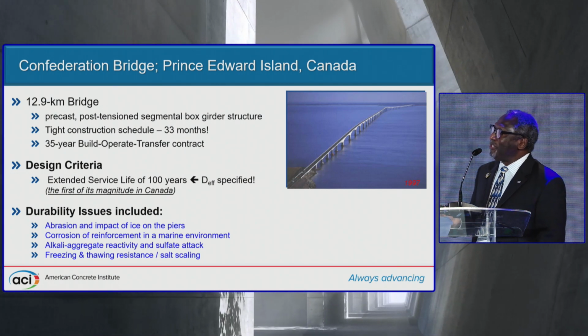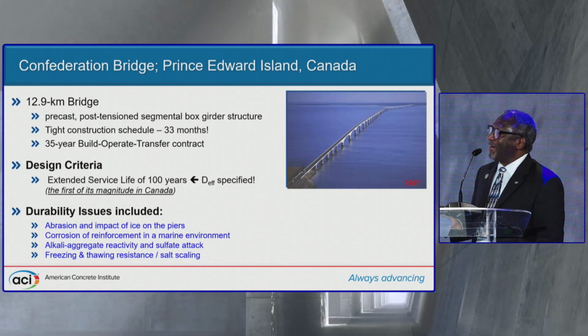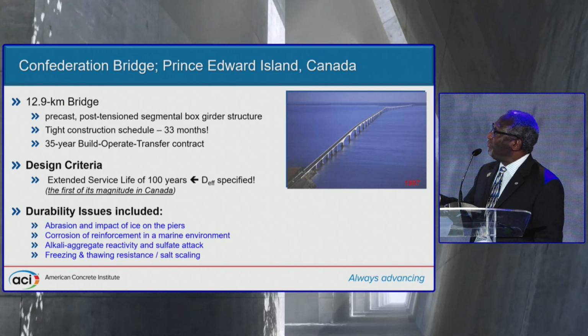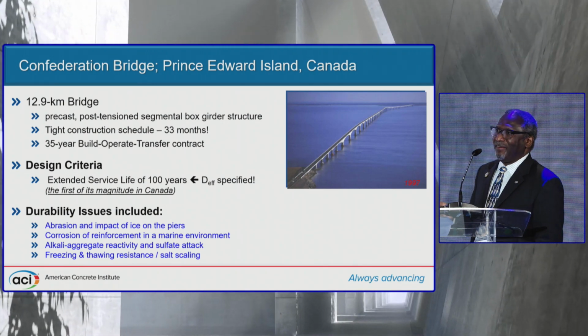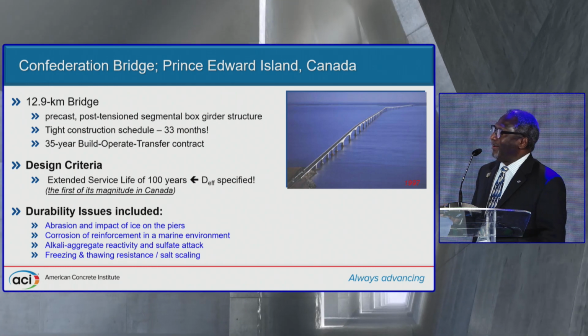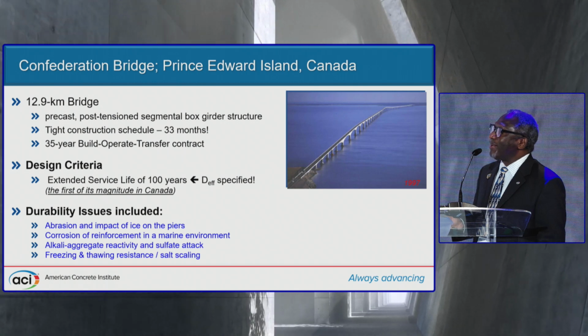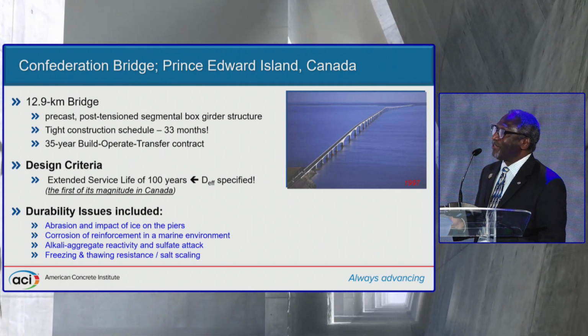Now, the durability issues that they also considered with this particular bridge included abrasion and impact of ice on the piers. So you can see here they have ice caps to protect the concrete. Corrosion of reinforcement, obviously, being in a marine environment. They were also concerned about alkali-aggregate reactivity and sulfate attack.